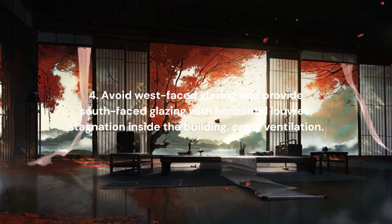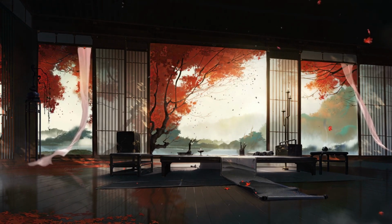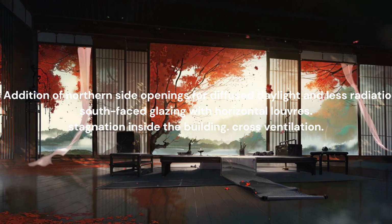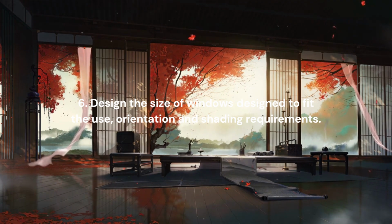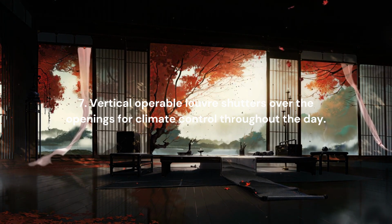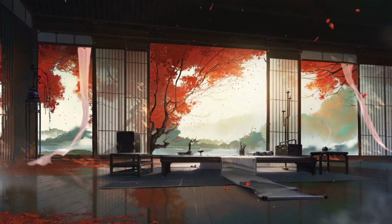4. Avoid west-faced glazing and provide south-faced glazing with horizontal louvres. 5. Addition of northern side openings for diffused daylight and less radiation. 6. Design the size of windows to fit the use, orientation and shading requirements. 7. Vertical operable louvre shutters over the openings for climate control throughout the day.